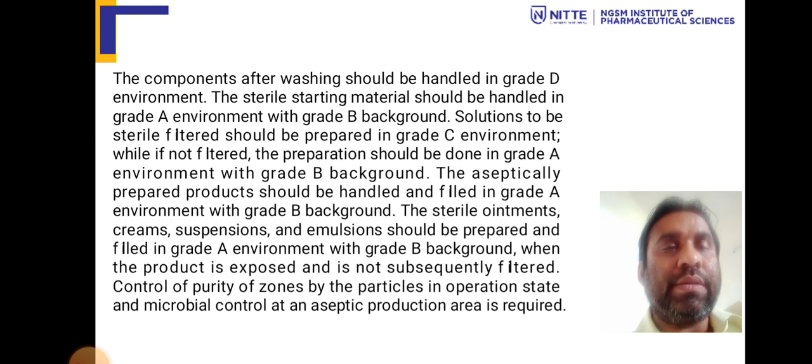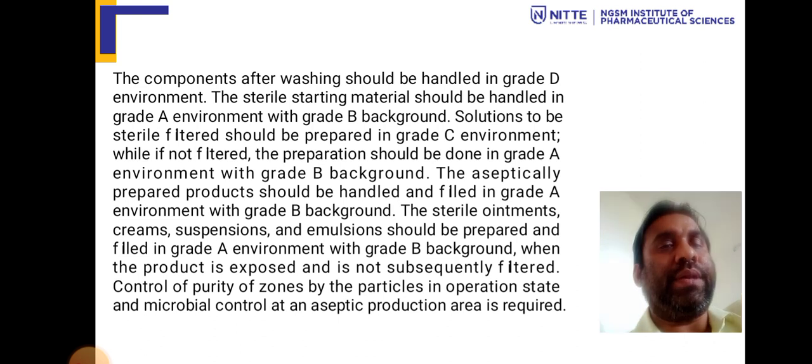Sterile material, starting material should be handled in grade A environment with grade B background. Solutions to be filtered should be prepared in grade C environment, whereas if not filtered, the preparation should be done in grade A environment with grade B background. Aseptically prepared products should be handled and filled in grade A environment with grade B background. The sterile ointments, cream, suspension, emulsion should be prepared and filled in grade A environment with grade B background when the product is exposed and is not subsequently filtered.